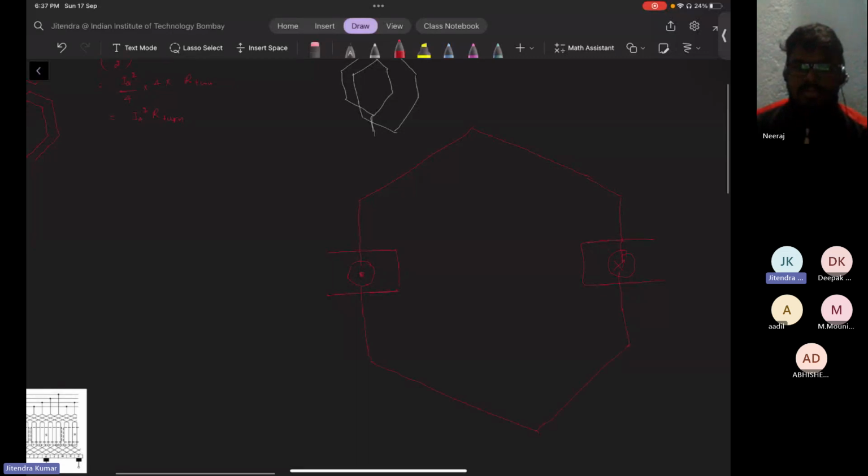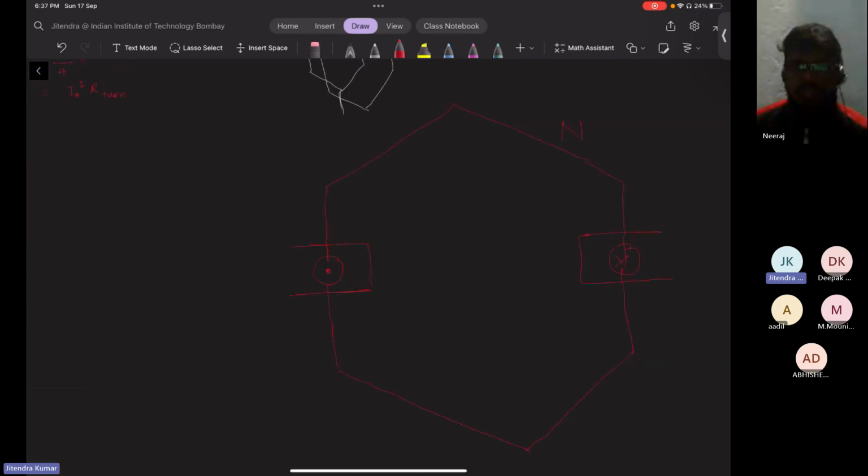With n number of turns, right? Multiple turns you can wound on a single slot or single armature pole pair. So which configuration does this particular winding have? We call this kind of winding simplex winding, because you had two slots, you just wound the two slots very simply, right? No sophistication, nothing.